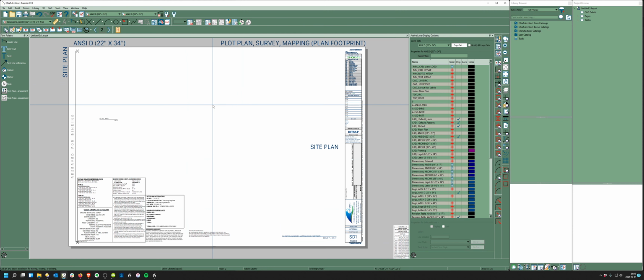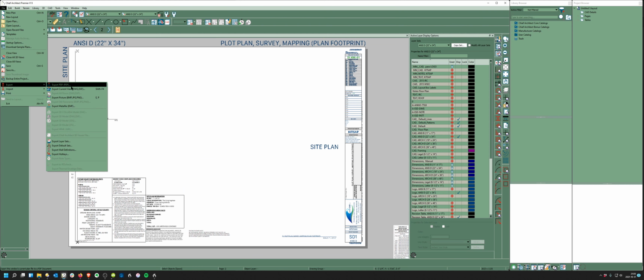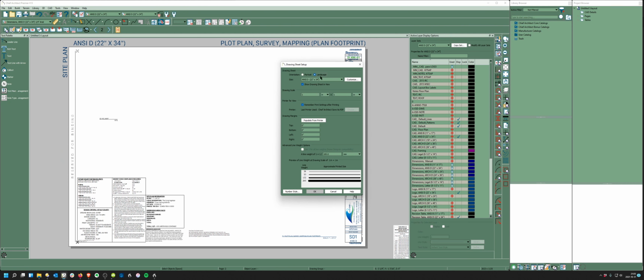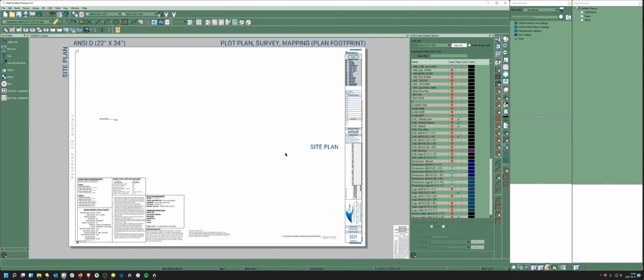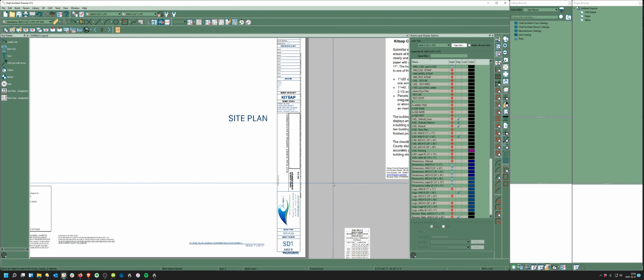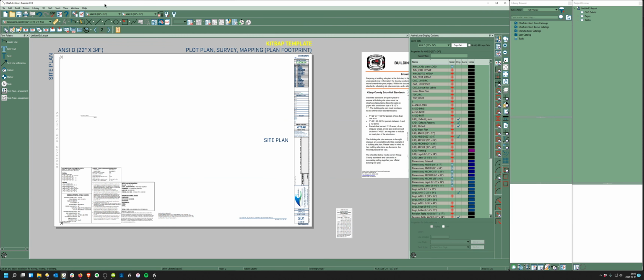So whatever scale you do, and that's easy to do: File, export, print, drawing sheet setup. You can pick whatever scale your drawing is going to be put on. Like I said, I picked ANSI D, but I used to always do architectural D. ANSI D seems to be working pretty good. And if they print it on 24-inch wide paper, you get an extra inch border, so you can put your grubby hands on the plans and it doesn't smear onto the important information.